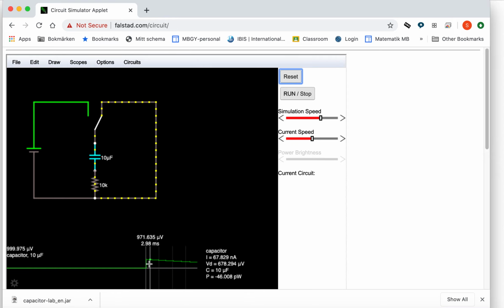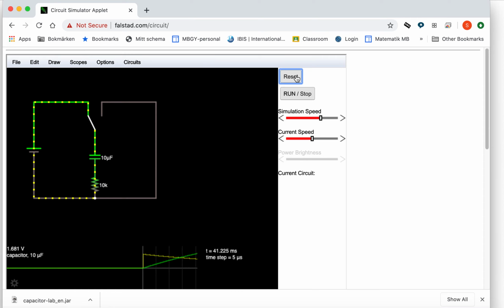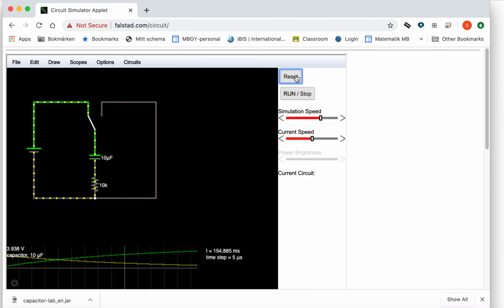Well, we've got a lower voltage, of course, because V equals IR, but it also takes a lot longer time to charge up. So both increasing the capacitance and increasing the resistance increases the time it takes to charge up and even discharge the circuit. And there are a few equations you have to know in order to solve charging and discharging, or rather discharging of a capacitor.